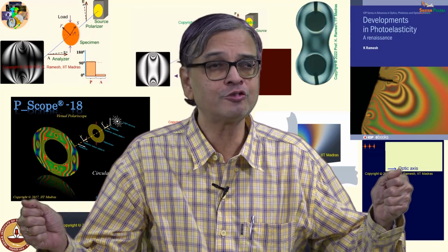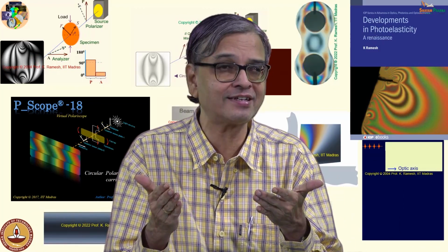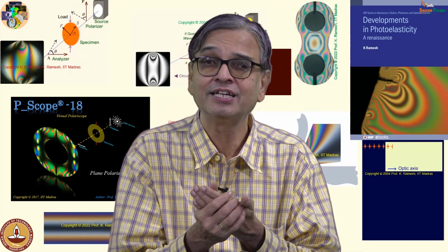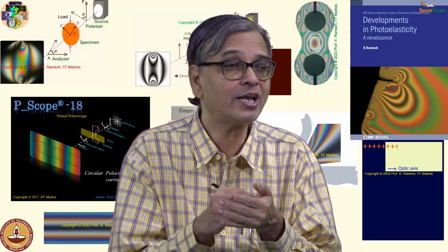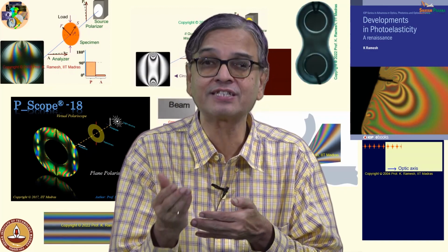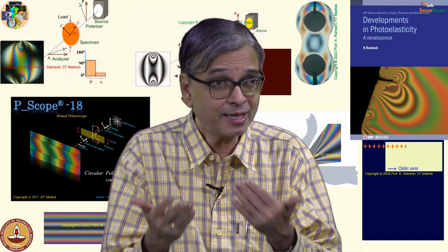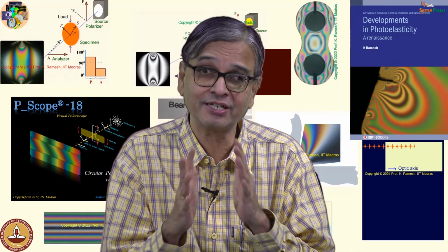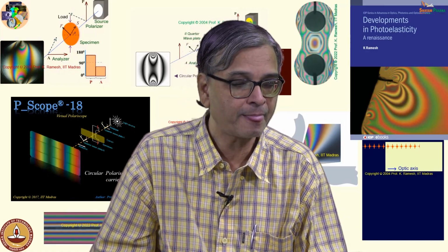This is a thick cylinder. Thick cylinder is the first problem you solve in the next higher level course. We have seen thin cylinder, you have determined hoop stress, and you have also determined, if it is closed, a longitudinal stress, and we saw that as a biaxial state of stress, and also caution that when you want to find out the shear stress, whether it is a local maximum or global maximum, you have to investigate. A planar problem becomes 3-dimensional. You can't always live in a planar situation. So, that is the caution that we have looked at.